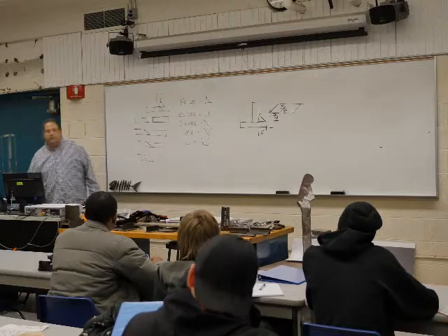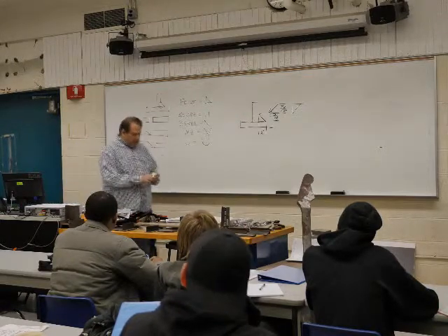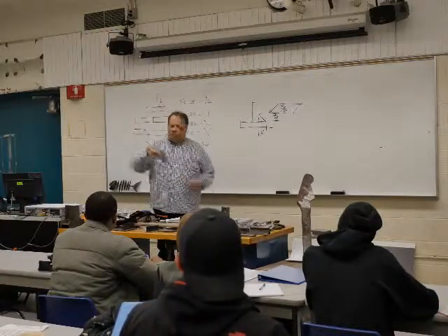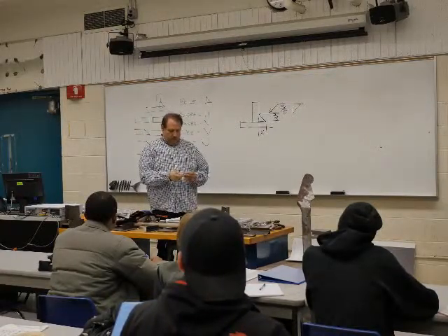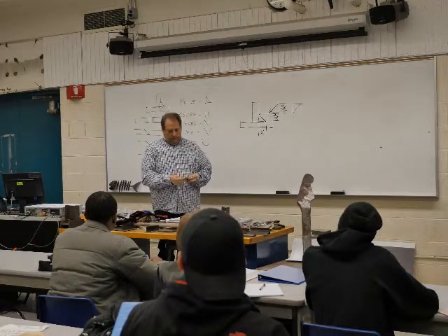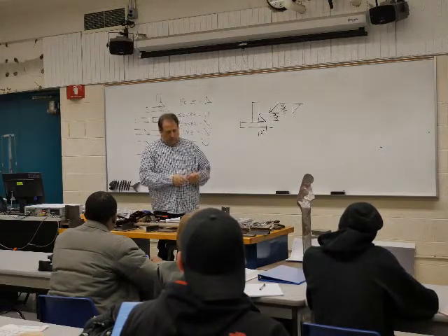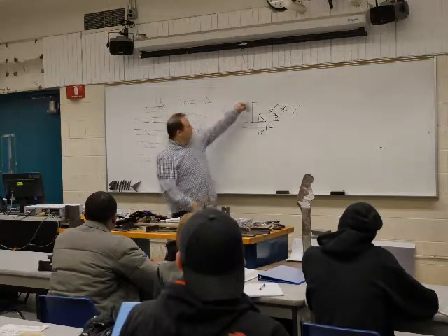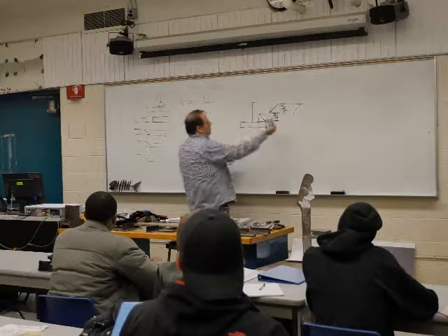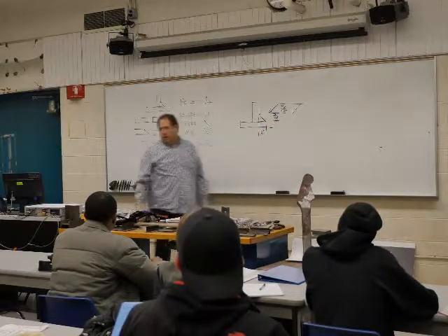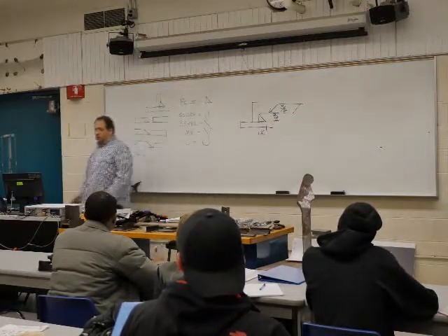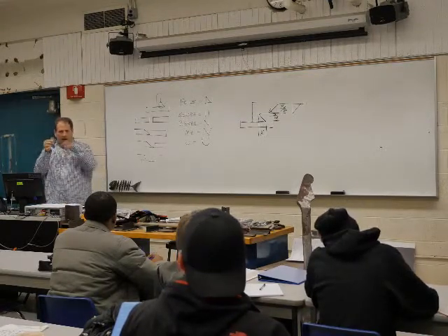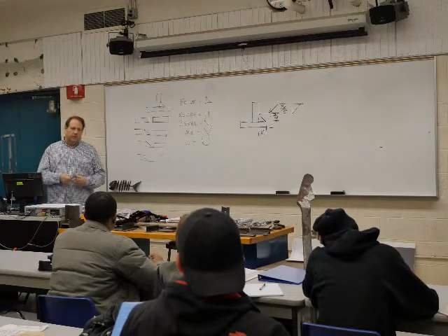We actually do have tools for that. This is a fillet weld, so a series of fillet weld gauges. Basically, you would take this guy. You go this way with it. You go this way with it, and that would give you your measurements. If one doesn't quite fit in there, then you have to find the one that fits to make sure about the measurements.